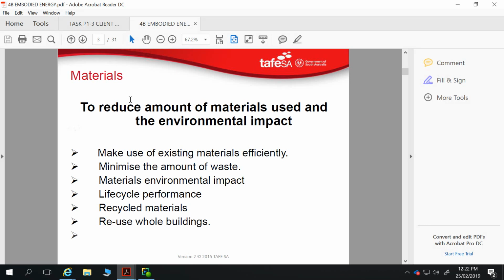Concrete trucks, if you're close enough to where they're operating, can take it back and make those great big concrete blocks, etc. But you probably don't really want to be wasting concrete. It's messy. You don't want to be wasting paints. You can waste a bit of roof sheeting, because roof sheeting can all be recycled. But you don't want to be wasting bricks and Besser blocks and things like that. They weigh a lot, and getting rid of them in the skip is hard. And you definitely don't want to be wasting plasterboard. When plasterboard breaks down it off-gases, and it's not very environmentally friendly.